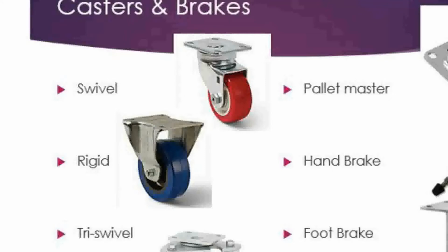One limitation for swivel casters is they have what is called a radius of rotation. Basically, you can't just quickly switch from one direction to a completely opposing direction with a swivel caster. It needs to be able to rotate around the caster's center of rotation, the actual center point on the caster plate that is attached to your object. So that requires you to actually move the object in a slightly circular motion to change the direction.